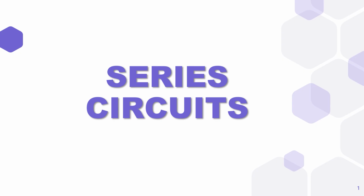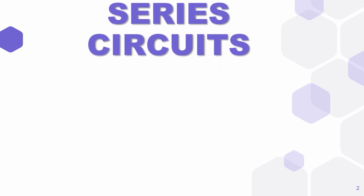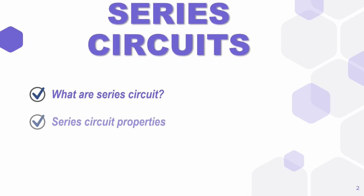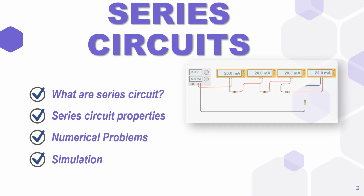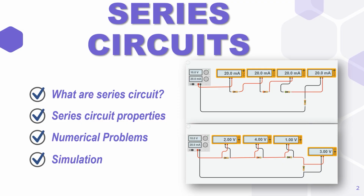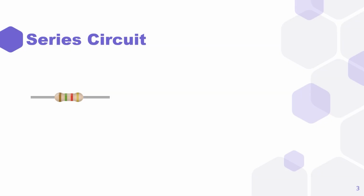Today, I am back with an exciting lecture on series circuit in which we will explore how we can connect resistors in series and will observe and practice their properties. We will solve numerical problems and will do simulation to validate our calculations. Let's get started. When we connect the resistors in such a way that second end of first resistor is connected with the first end of second resistor, they form a series circuit.